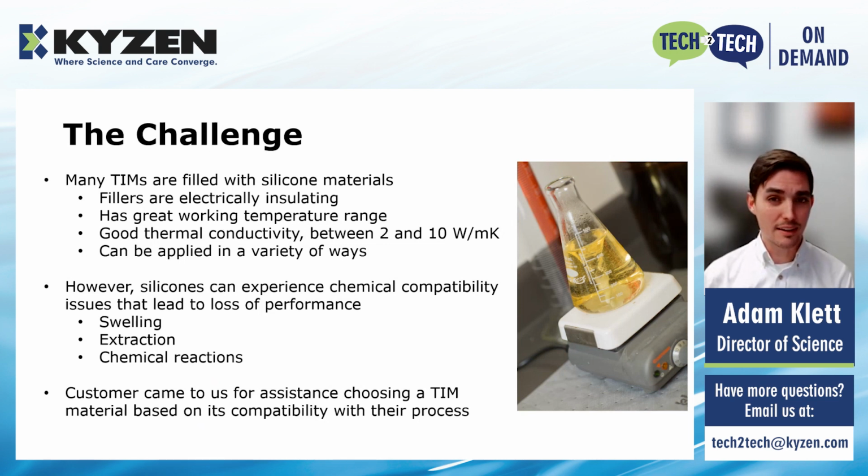And they can be applied in a lot of different ways. They come in many different forms. They can come in pastes that can be dispensed. They come in pads that can be preformed to the right size that can just be placed on top of the components. And they also have multiple curing mechanisms. You can find TIMs that require a thermal cure, or maybe TIMs that require a two-part mixture that requires a room temperature cure, maybe a moisture cure, or some that don't even require a cure at all. And so there's a lot of materials out there that you can choose from to meet your process needs.